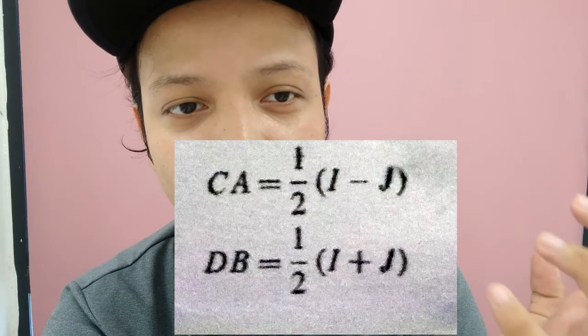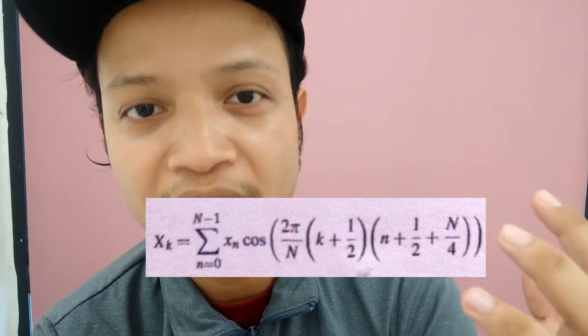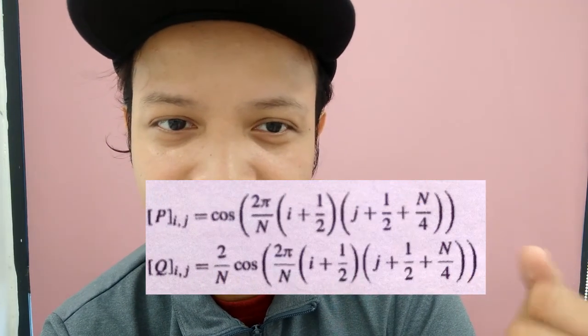where J is the counter identity matrix. The forward modified discrete cosine transform is given by the following equation, where Sm are the audio samples and Sk are the frequency coefficients. The inverse MDCT is given by, or in terms of our matrix notation, thus, while the inverse transform for any one block will contain aliasing, by using the inverse transform of neighboring blocks, the aliasing can be cancelled.